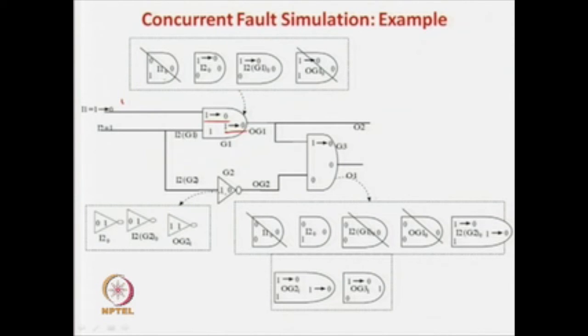Now, this gate corresponded to a stuck at 0 fault over here. So it was a 0 over here, 1 over here and a 0 over here, correct. This is the old thing that is retained. Now your normal gate will become 0, 1 and 0. This is your normal gate looking like 0 1 0 because this pattern you have to change. So this gate, which we are going to delete, gets deleted.